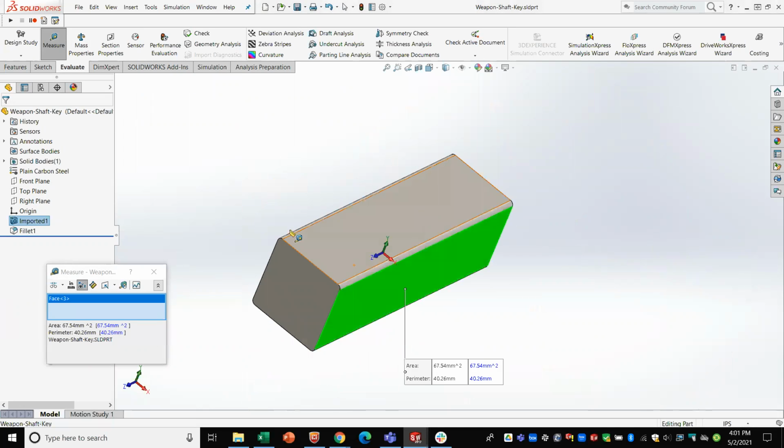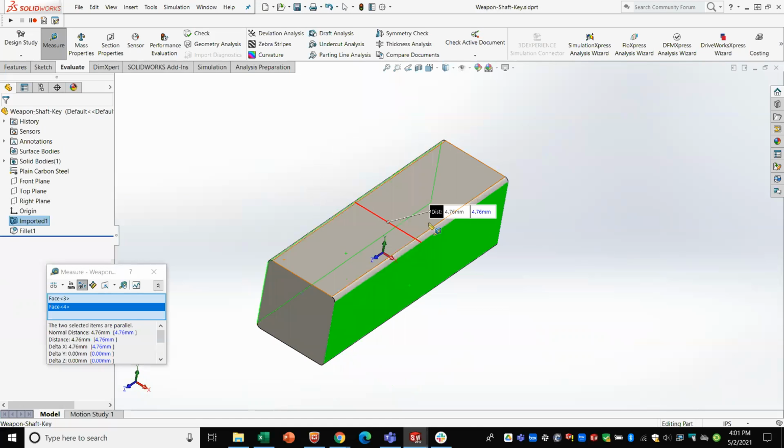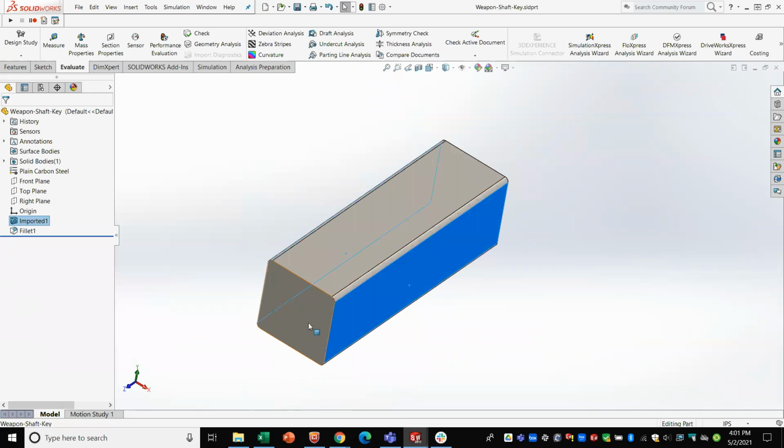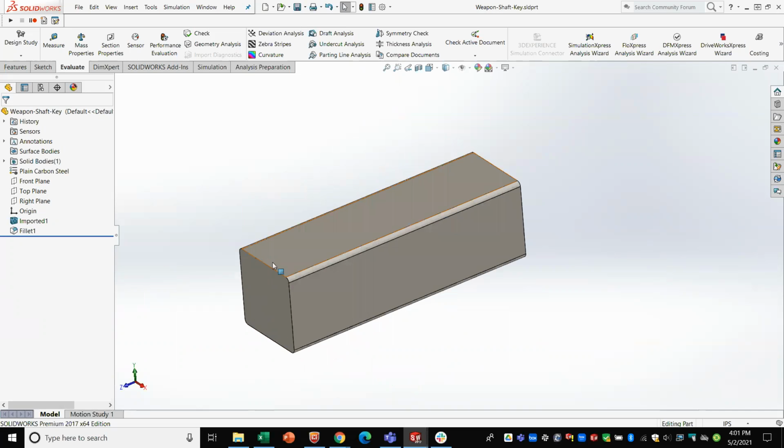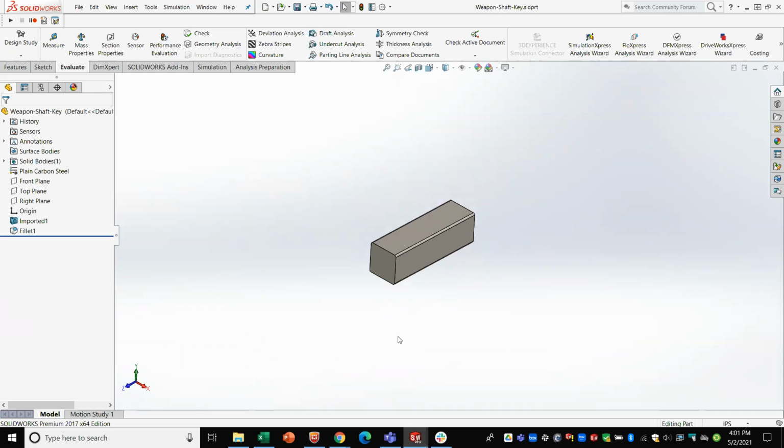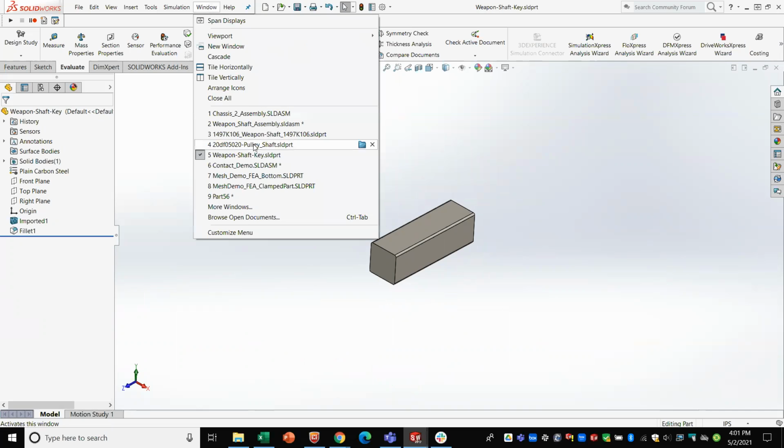And then it is 4.76 millimeters wide. So you look at the shear area of this cross-section times the shear strength multiplied by the radius from the center of rotation, and that'll get you the torque that key will fail at. All right. Yeah, that makes sense. So you want to make sure that the key is wide enough.